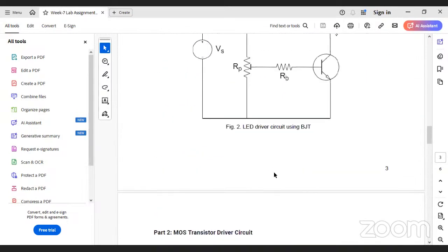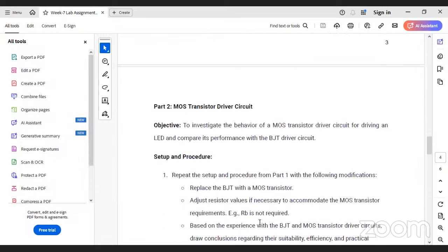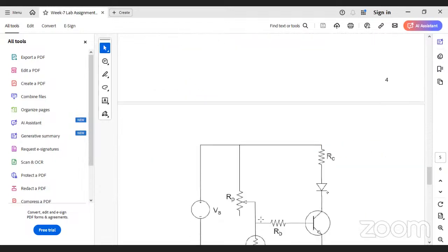I think this problem is solved, but I'll also confirm once. Better. I think I did this. Removed this, disabled this thing, the repeated sweep, and then I got constant voltage once I did that part. Okay, so I think everybody has also confirmed that disabling the repeated sweep will give you a constant